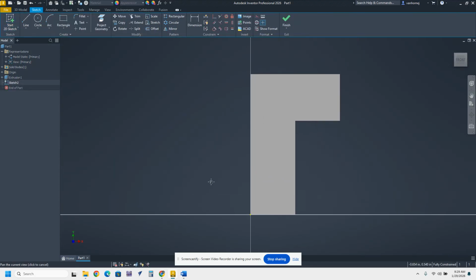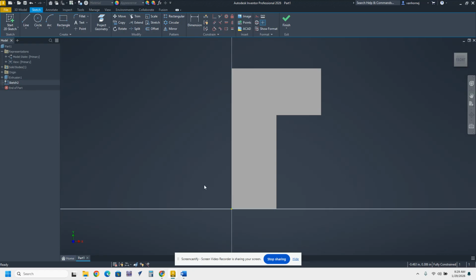So right click, new sketch, click that face. It's now going to reposition my shape so that I can draw my 2D sketch. Now what's interesting about this is that in this case, I may not want to use my origin, which is here, as the starting point. And you're going to see why that is the case. I'm going to go to my line, and I'm actually going to start here. So you can see the mouse does snap to that corner. It's got a little bit of a yellow dot in the middle, but as I move the mouse closer, it turns to a bigger green dot. I'm going to start my sketch here, and I'm going to draw up 0.75.